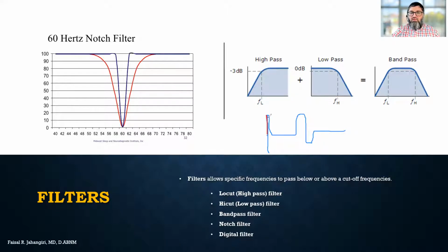It is the ringing of the stimulation artifact, not the ringing of the signal. That's a very important point to remember. Instead of stopping at zero, the stimulation artifact will keep going on, and it will superimpose the response depending on how early the response is, and we will not be able to see the response. So this ringing will distort the signal.